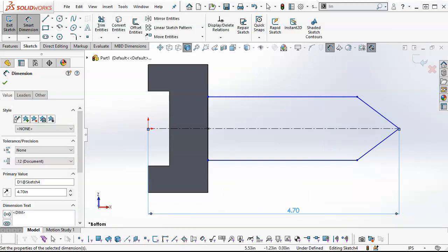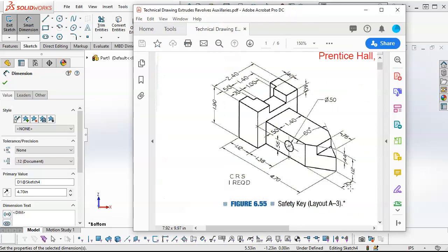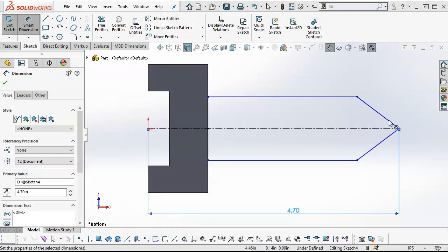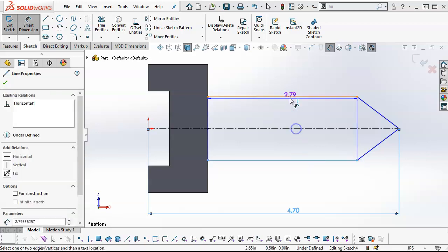The width of the tab is given as 700 from the center, and that may be a little confusing. In terms of adding that 0, even if it's 1 inch 120, 4 inch 440, or 440, 760, it puts it into thousandths of an inch, which is going to be the more common terminology we're working from. I'll try not to make that too confusing. All right, so off of the center line, 700, or if we go from line to line, we can go 1 inch 400.